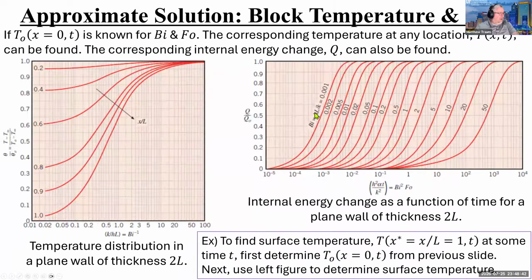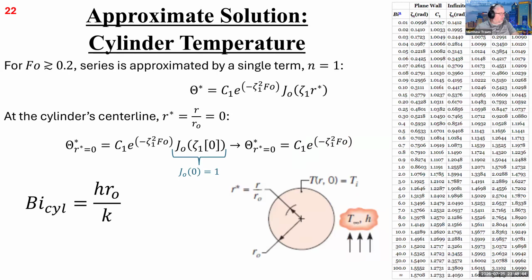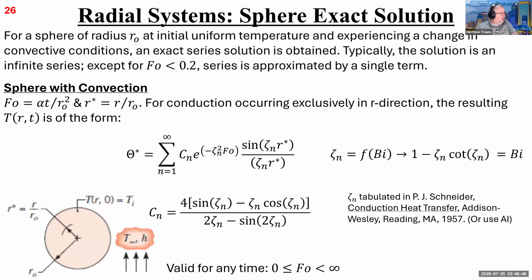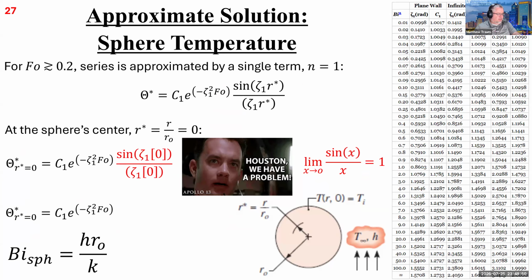So again, this feels really daunting and complicated, but the solution pathway is the same every time, regardless of the geometry, and everything just collapses onto itself, right? So how would you attempt to find the temperature of any spot inside a sphere at any time? Well, you find the Biot number, right? And that's how we get here to begin with, because if the Biot number lets us do lump capacitance, we want to do that. But if it doesn't, then we're here.